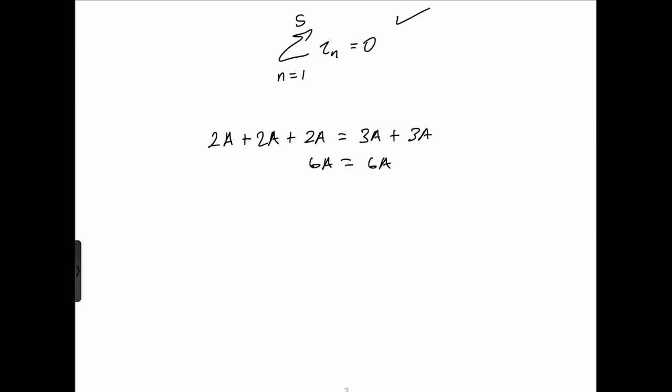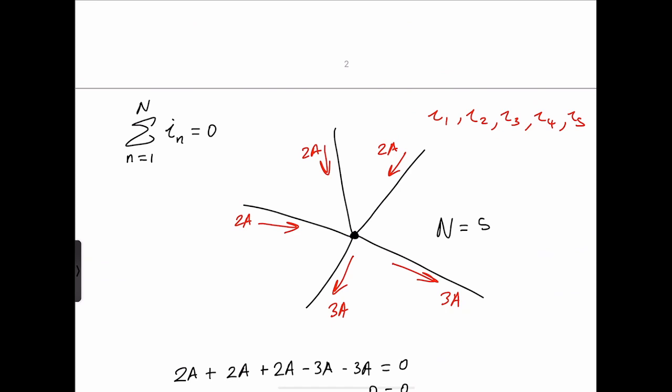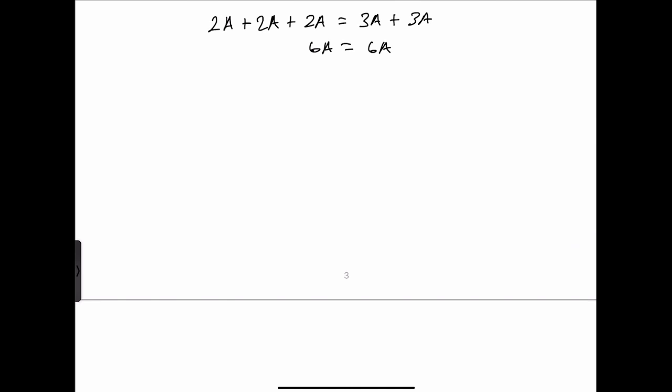So another one is Kirchhoff's voltage law, KVL. So we should just write that here. This is KCL. Oops. This one is KVL. And Kirchhoff's voltage law states that the algebraic sum of voltage around a closed path or loop is equal to 0.